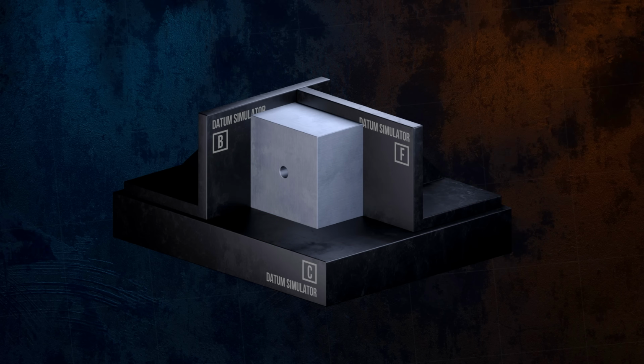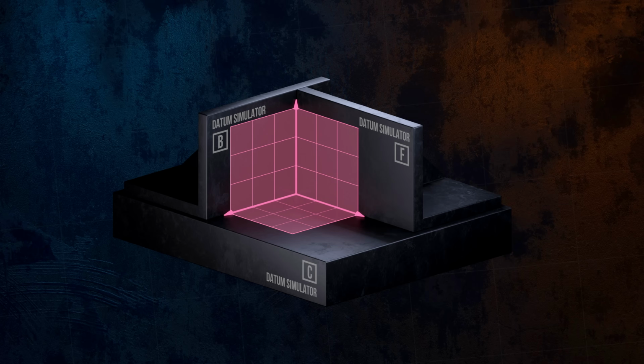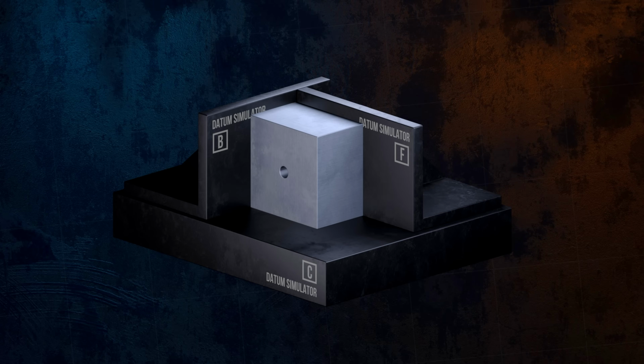These datums establish a datum reference frame, the coordinate system used to inspect the feature. The order in which the datums are applied is important, because all real surfaces are imperfect. Using datums in the same order ensures that measurements are repeatable.